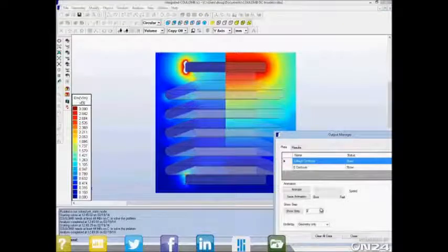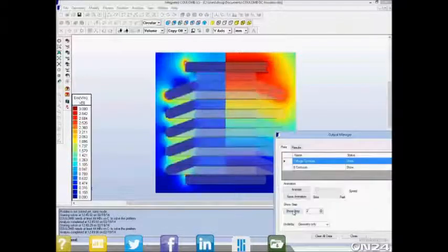If we go to step two, our conductivity mode solution, now you can see that because the voltage is basically driven by a current that runs down the center, a very weak current, but a current nonetheless, the voltage varies more or less uniformly down the center, and therefore the field is also quite uniform running down the center. And then these sheds that stick out, there's no current running down them, so they will maintain a close to uniform voltage.